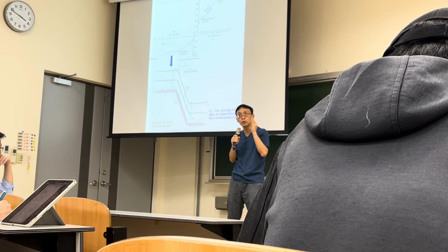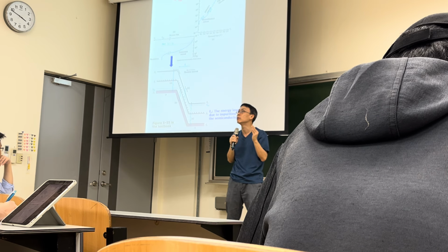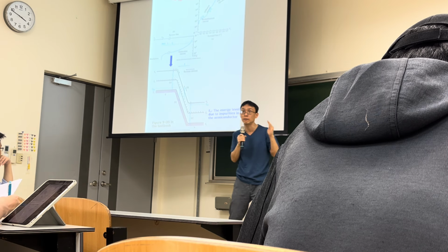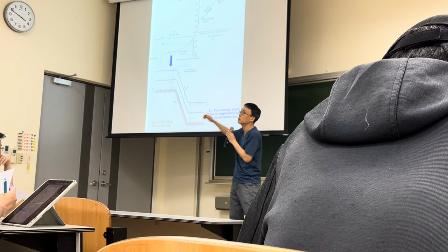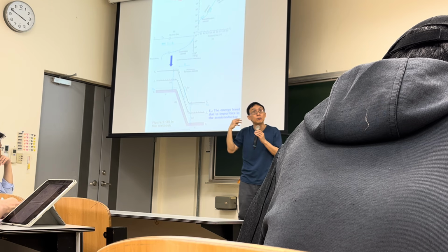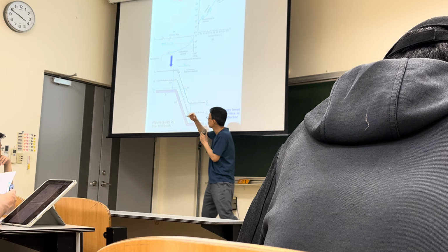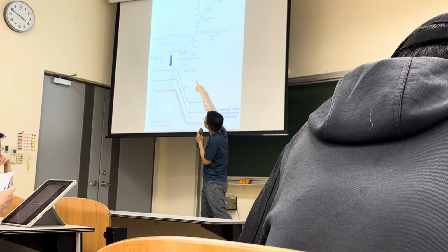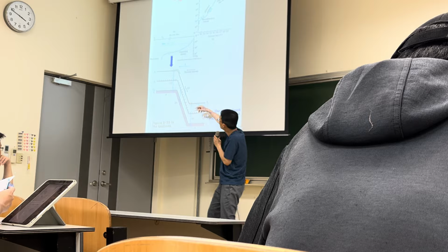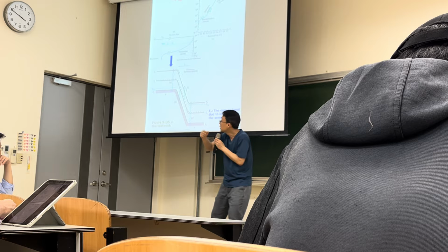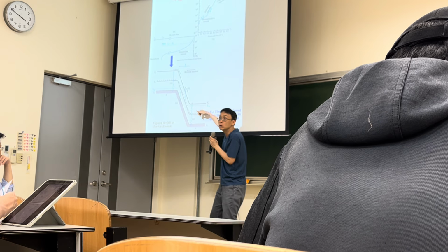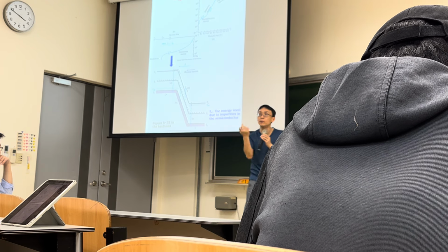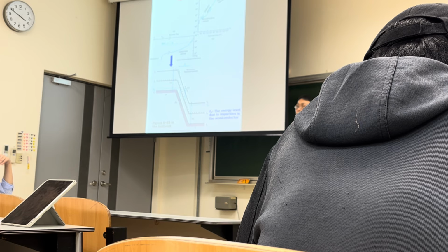You can use the PN junction again, as long as you don't enter the avalanche breakdown. So you know the difference between avalanche breakdown and the generation current. Avalanche breakdown is from the excitation of electrons in the valence band. But the generation current, the blue line before avalanche, is from the electron in the impurity level, not the valence band. That's a big difference. Do you know the big difference?